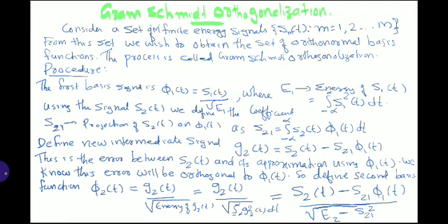So this Gram-Schmidt process exactly gives that. It gives a set of basis functions which can be used to represent our signal s_m(t) as a linear combination, so each s(t) will be converted to a vector in the space spanned by phi(t). So we'll study what the procedure is.